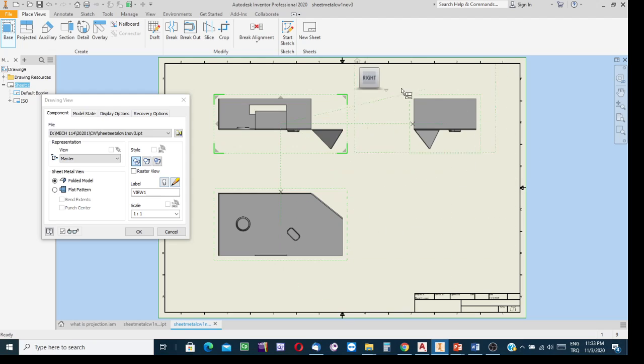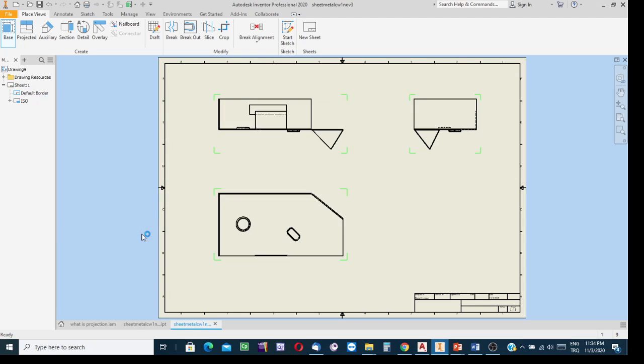These views, principal views, are to inform the reader on the appearance of the object. These are not so valuable. The valuable drawing is the one that shows the sheet metal work as unfolded. It is the figure actually to draw over the surface of a flat sheet. And then if there is a cutting, cut it along the edges, and then the rest is folding the sheet metal, then set it to its final form. Okay, well, here my purpose is to create the views of the sheet metal work, not the development. So this radio button is correct, and then say okay.